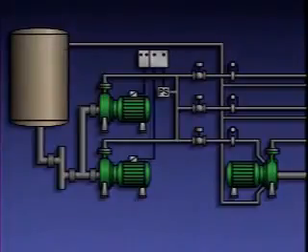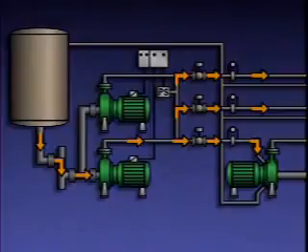During operation, the supply pump draws the oil from the storage tank through the filter. The filter removes contaminants from the oil to prevent damage to the sealing system pumps and the mechanical seals being supplied. The pump supplies the oil to the pressure regulators on each supply line. The pressure regulators control oil pressure and the amount of oil flow to each of the mechanical seals. The flow meters allow the flow to the seals to be monitored.